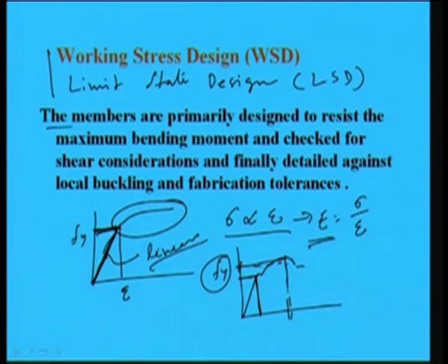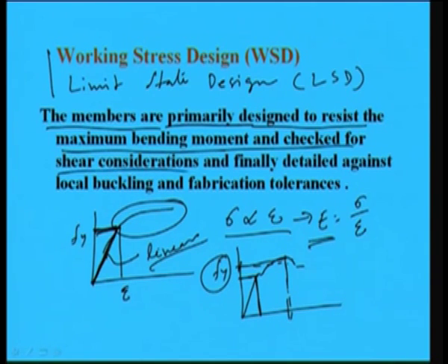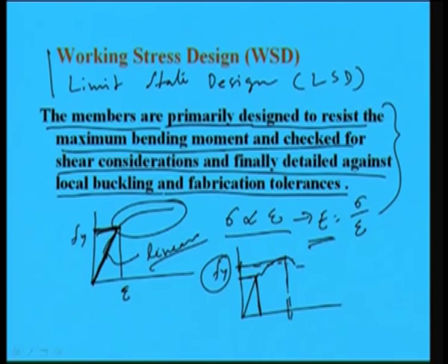Here you see the members are primarily designed to resist maximum bending moment and checked for shear considerations, and finally detailed against local buckling and fabrication tolerances. So, the entire design method will be based on this philosophy, right. I am repeating once again that the members are primarily designed to resist the maximum bending moment and checked for shear considerations, and finally detailed against local buckling and fabrication tolerances.